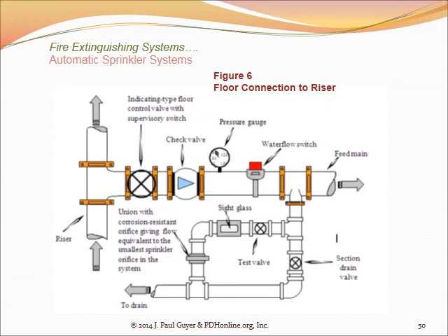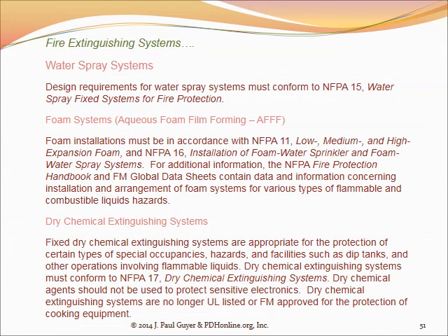And then there's the supplemental piping there for testing the piping on the floor, and to drain the piping on a floor for maintenance purposes. Anyway, this is more or less what you have at each floor in a multi-story building. Now, that's water being used as the medium for putting out the fire. There are other things you can use to put out a fire.